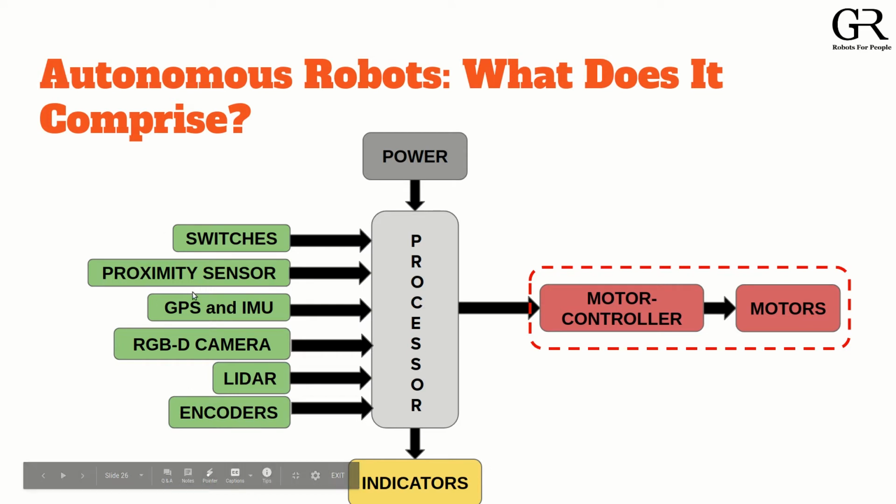So you can distribute your entire system not only on a single processor, but amongst all the different small processors, and integrate them into a single system. In this way, the hardware side of your autonomous robot is divided, and all the different nodes or controllers communicate with each other. Each node handles its own specific task. A node can handle motor actuators, a few nodes can handle your low level sensing, and there are different nodes which handle the RGBD or lidar camera. In this way you can divide your entire system into multiple distributed units.